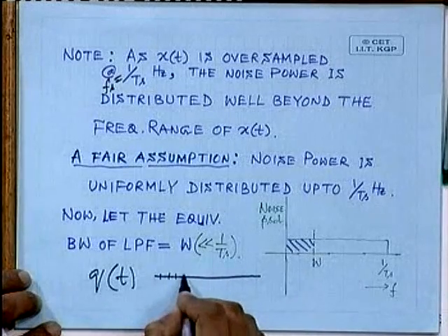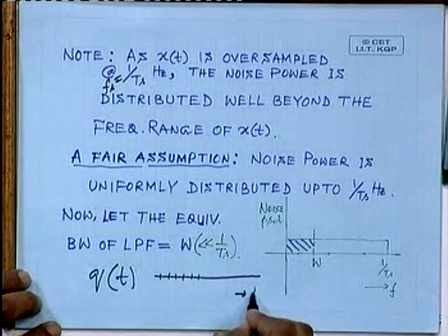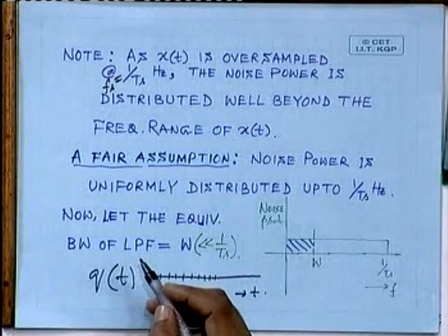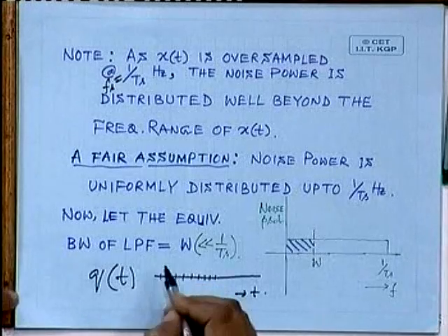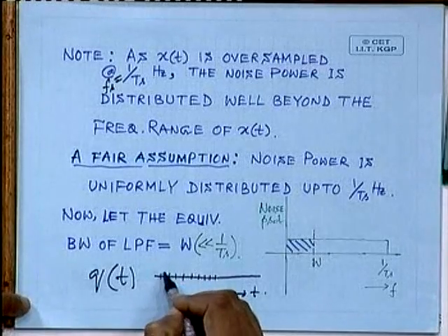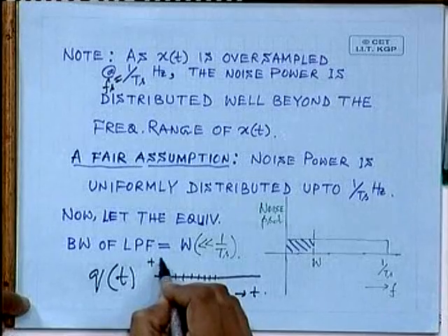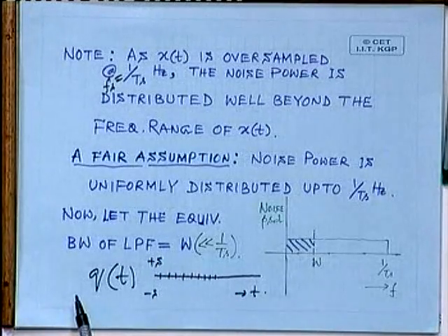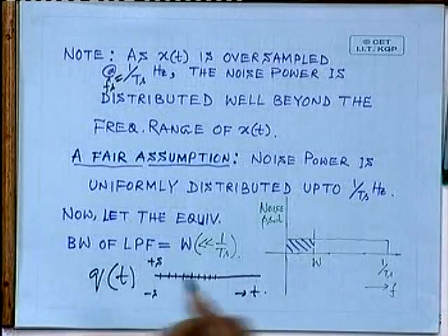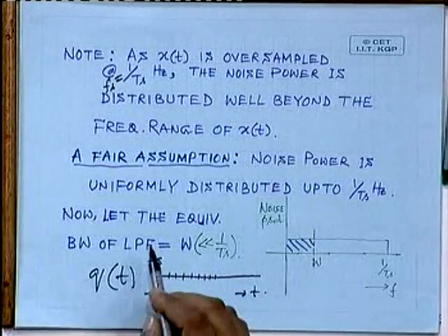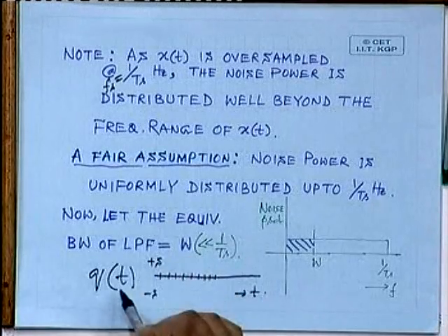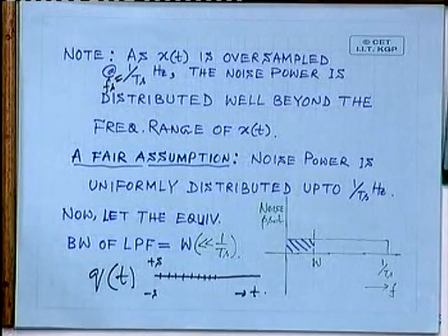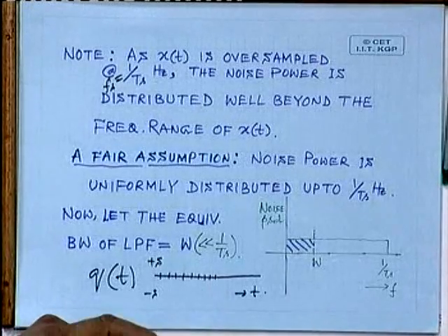See, if I say this interval is Ts against t, every Ts the quantization error is changing, is it not? So, it is ultimately between plus S and minus S, but it is changing at a very fast rate. Fine. So, I can say that this quantization error will occupy a larger frequency band, much more than the signal frequency band.